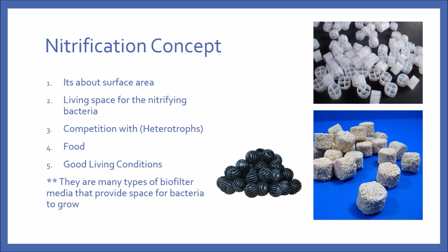Note that there are a lot of terminologies for the same thing. A nitrifying reactor or biological reactor is simply where this process takes place. An important concept about nitrification is to provide enough surface area for the bacteria to grow on. Also provide them with adequate food, good living conditions, and protect them against competition from other types of bacteria.